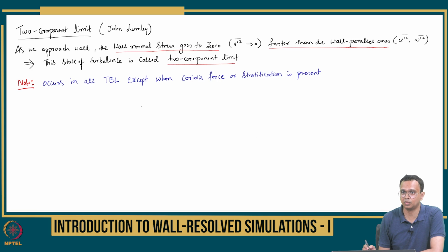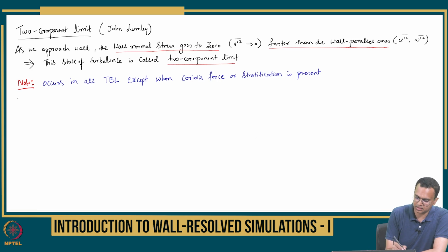And does your model model this? So eddy viscosity model has a problem because the isotropy is enforced through eddy viscosity and turbulence kinetic energy in the Boussinesq, right? So EVM models, you can say eddy viscosity models, have an issue here.